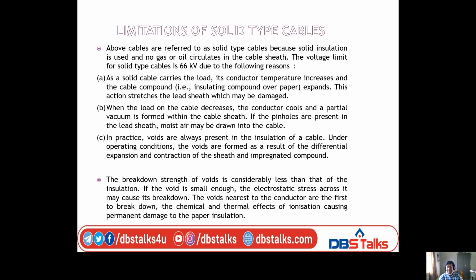When the load on the cable decreases, the conductor cools and a partial vacuum is formed within the cable sheath. Then if pinholes are present in the lead sheath, moist air may be drawn into the cable. If load increases, the conductor temperature increases such that the cable may increase its cross-sectional area. That means it may expand. So that may be a problem for the lead sheath.